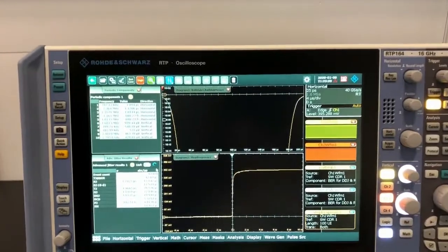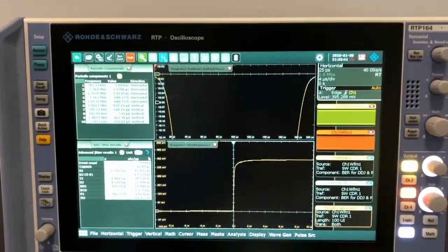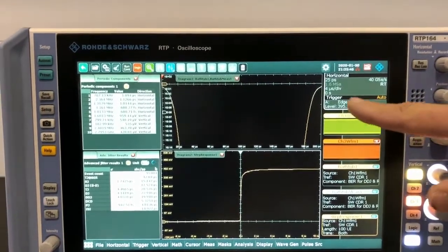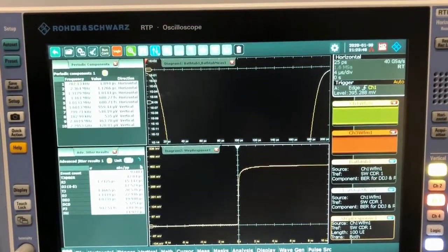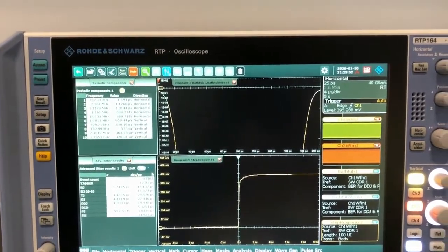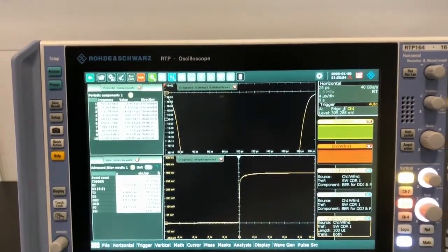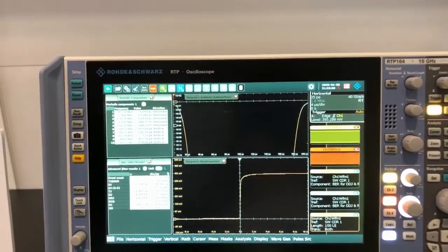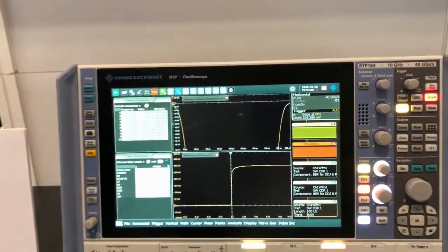Now one of the other interesting things about our jitter software is that because we're using a signal model to do the measurement, if you look at the record length size, it's only 1.6 megasamples. If you know jitter measurements, typically you want 20, 50, 100 megasamples. But because we're using the whole waveform, we don't need that much data to get the jitter measurement. So it's a much more efficient process than currently exists.